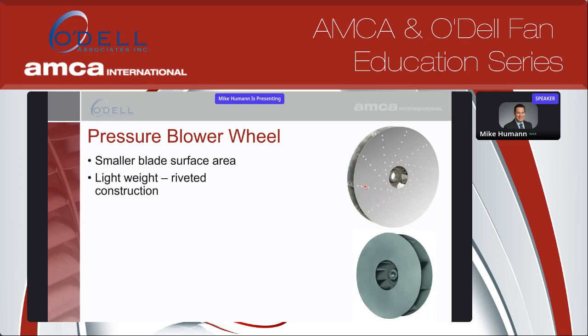The aluminum can't handle a lot of temperature, and it cannot handle any material. So it's lightweight and lower cost, and because of the weight advantage, you can certainly handle higher speeds, provided that the application has clean air. Down below, you do have a steel wheel, so you do have some flexibility, but that wheel is also not as efficient as the aluminum wheel. So you do have a trade-off there.